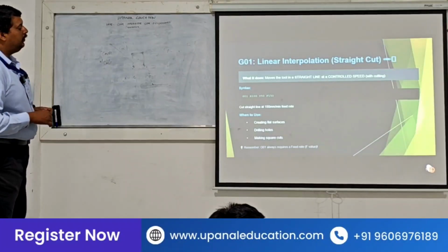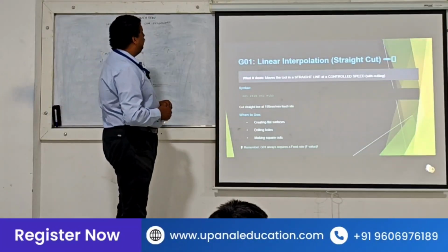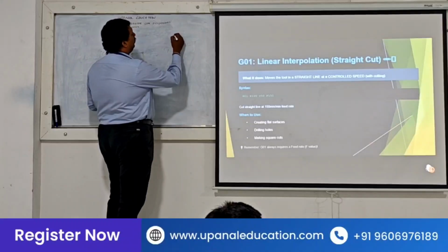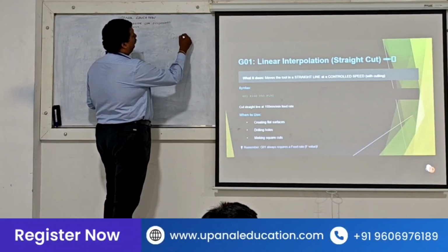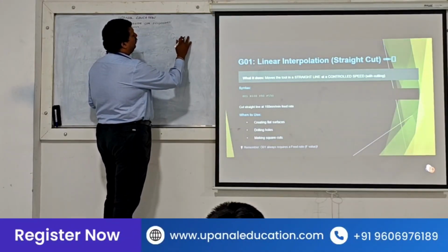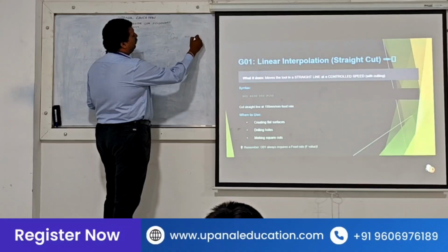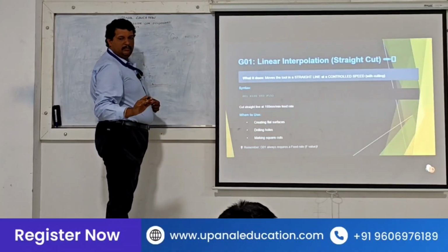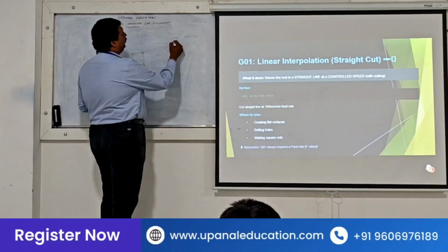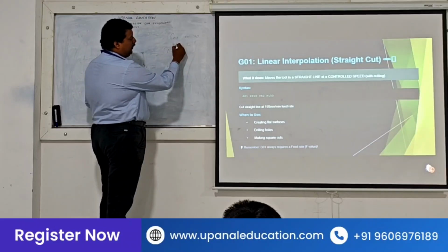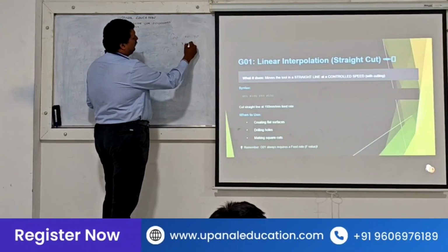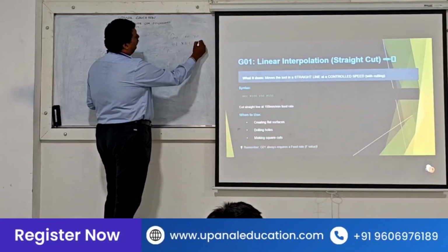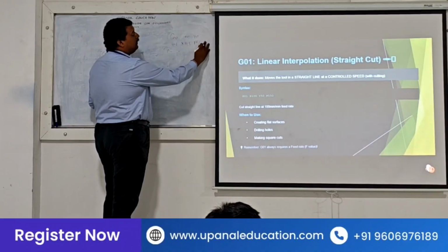So how will it be? Earlier I told G00, for example, X0 Y0. Now next, G01: go to X100, Y100, and I will mention the feed here.